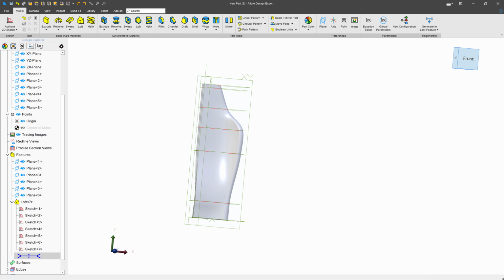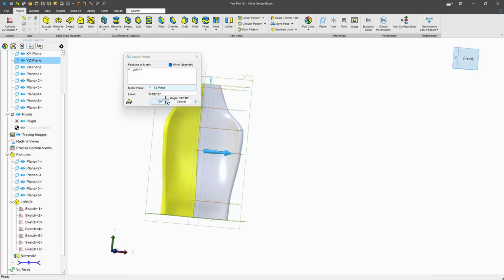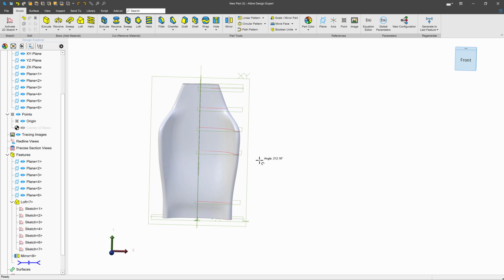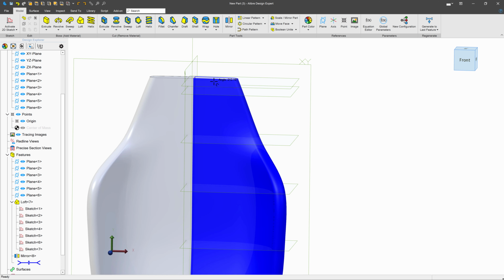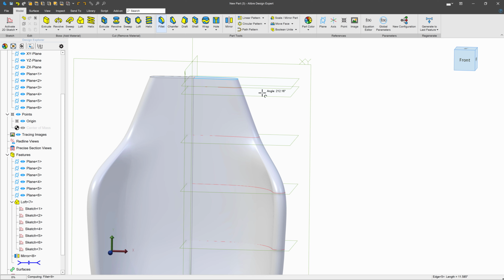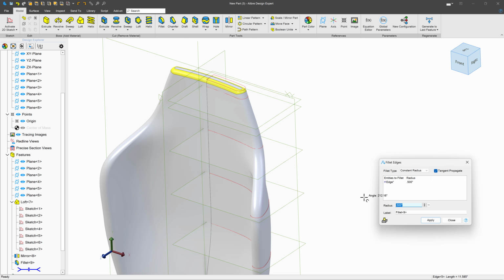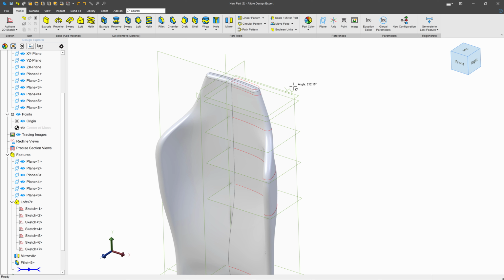So next, I think an easy thing to do would be to take a look at what our chair looks like full on. So we'll grab our loft, we'll mirror it just like that. As you can tell, I think that's looking like a pretty good gamer bucket seat chair. I'll grab the top here, and we'll simply add a fillet. And it actually looks like 0.5 works pretty well, but I'll up it to 0.575. So a nice rounded top. And we'll probably want to make some harness cutouts. That is pretty typical among chairs like this.